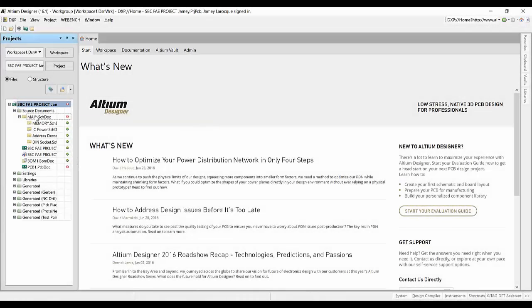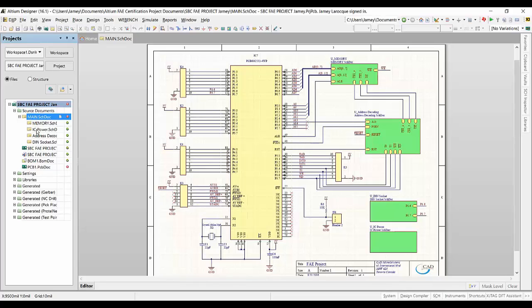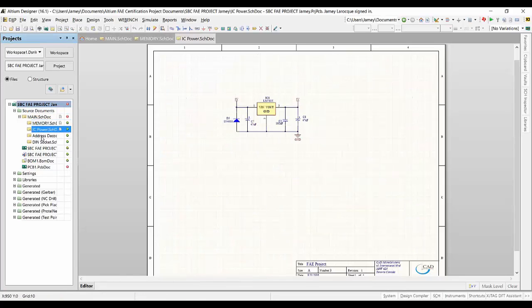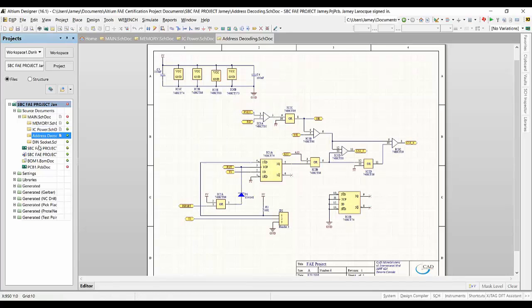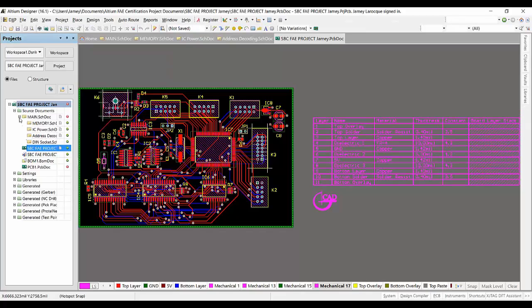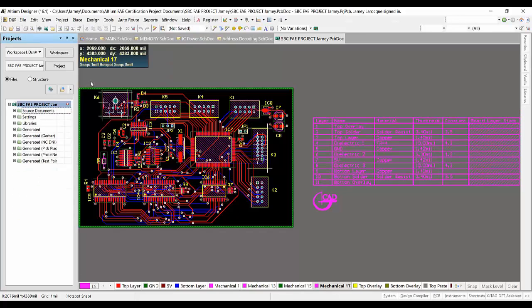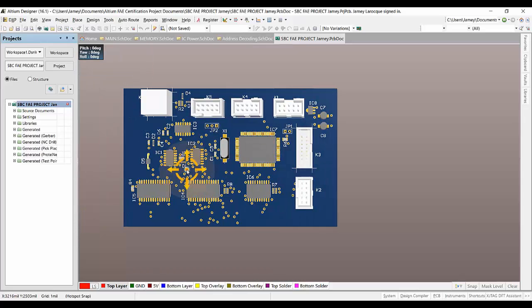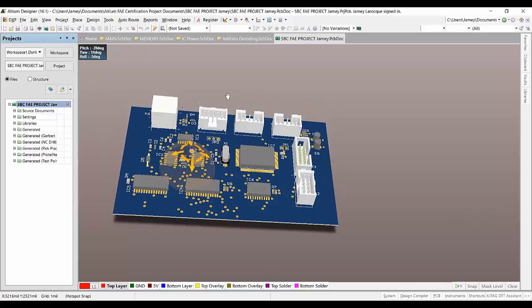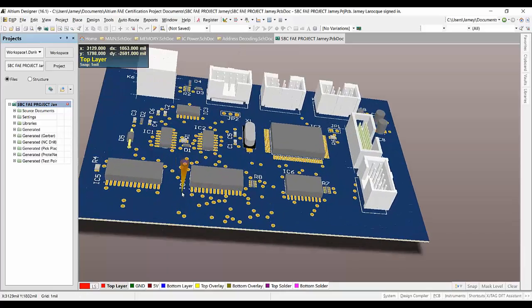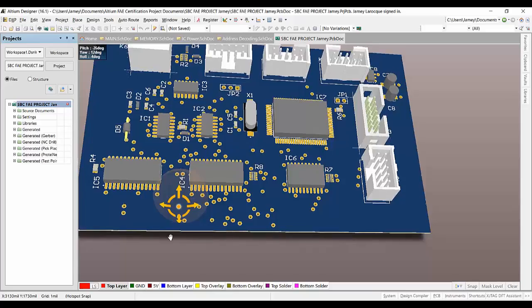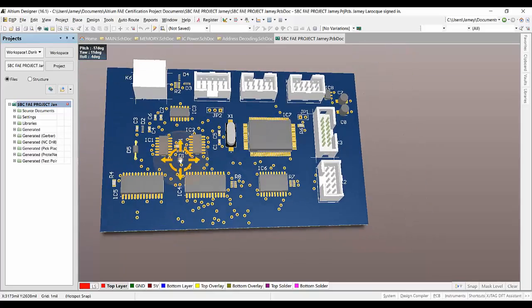Altium Designer provides a unified electronic product development environment catering for all aspects of the electronic development process, including front-end design and capture, physical PCB design, and other electronic developments such as mixed signal simulation and signal integrity analysis, to name a few. Within this unified platform, Altium is capable of generating all manufacturing outputs such as Gerber files, ODB++, and C-drill files, along with other files such as a bill of materials.